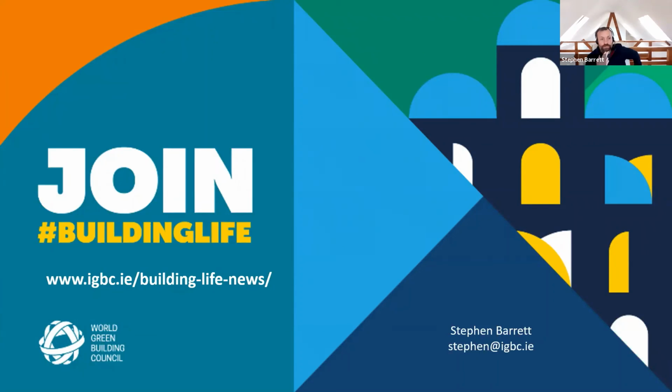Yeah, so an EPD is carried out by a third party. A manufacturer employs an LCA consultant to come into their manufacturing process and understand it. Then the consultant goes away and models that process in LCA software, which is not quite the same as what we're looking at when we talk about building level. This is a more granular component level. So it's not done by the manufacturer, it's done by an independent LCA consultant, and then it is third-party verified by another LCA consultant. So it's as good a data as we can get.